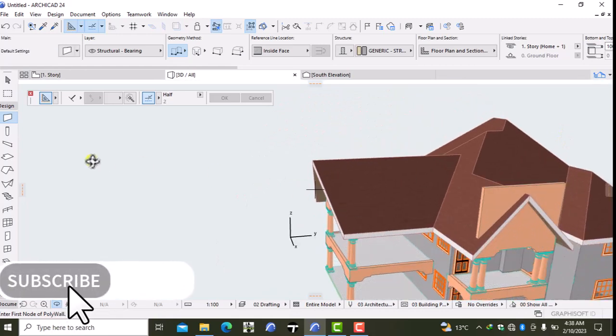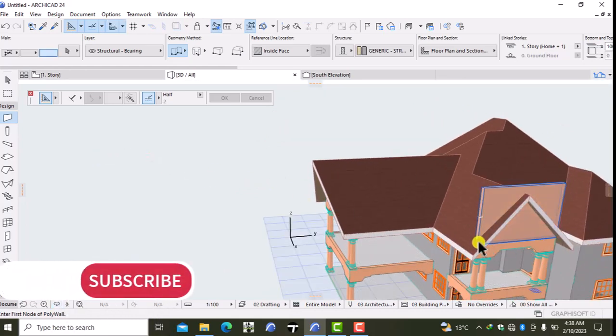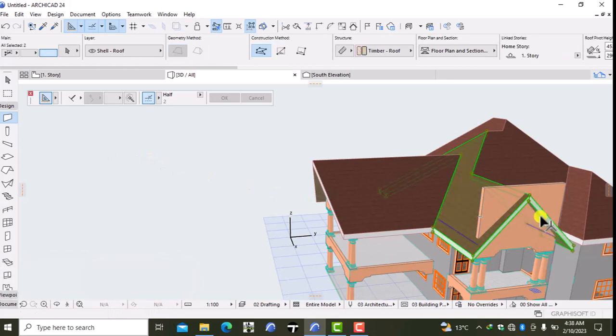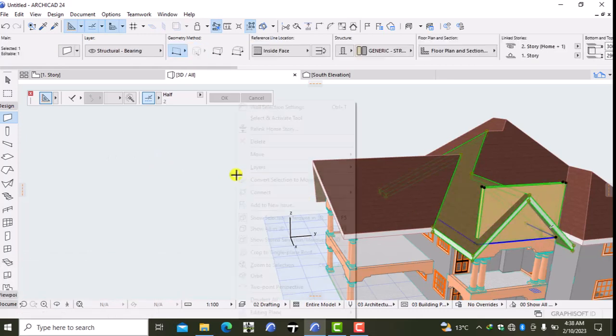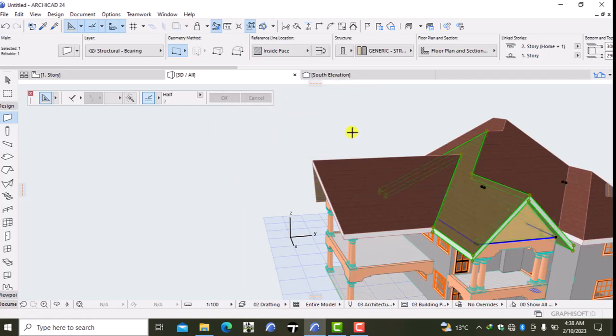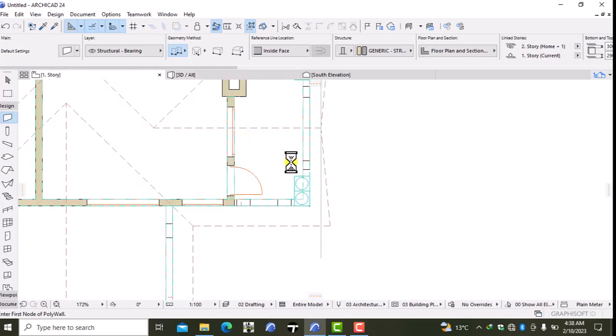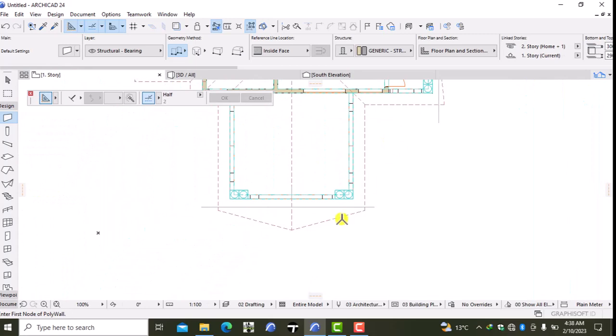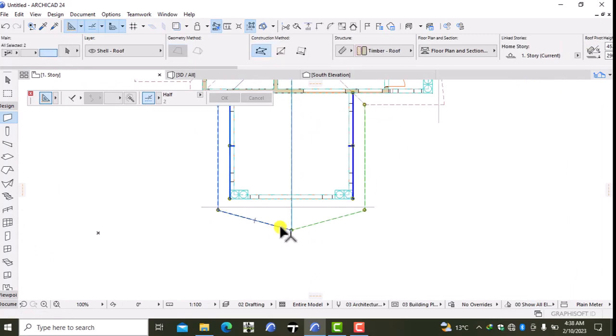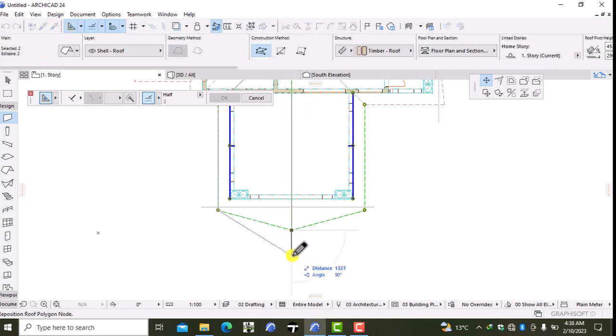Just go ahead now, come to this edge, select these planes and the wall, right click, connect, trim, yeah, trim. So yes, and that's what I need also to set this the way we did for this other one. I especially feel I should have dragged this a little bit to the front, maybe a distance of, let me see if I do an additional 1200.